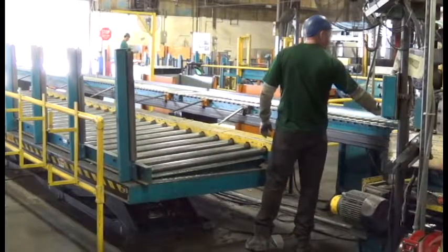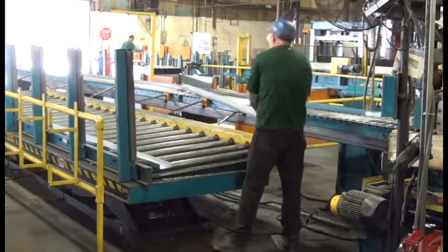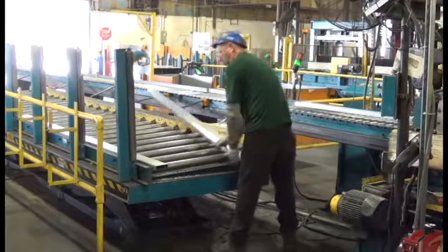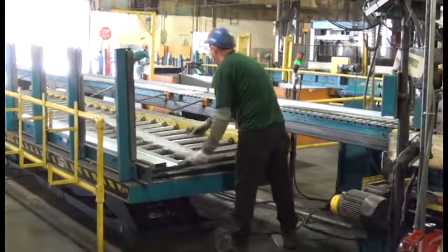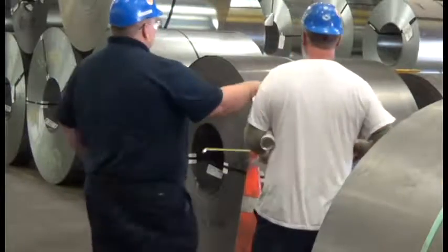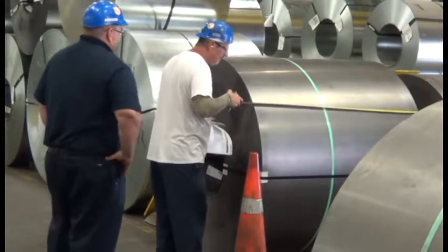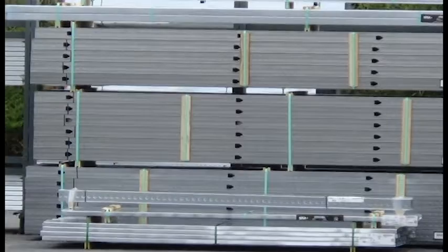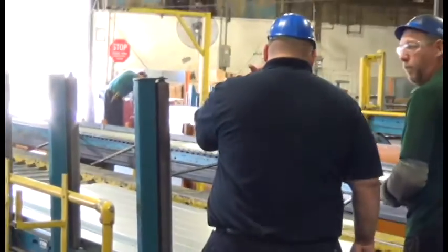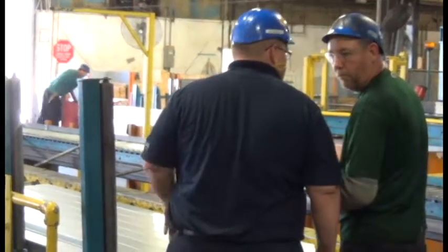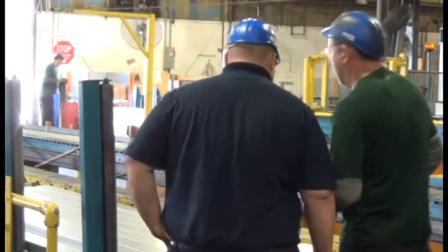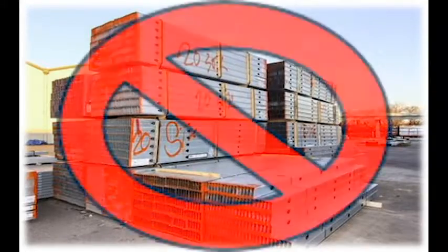A key benefit of traceability to the manufacturer is that if a stud or track fails a performance specification or does not meet minimum requirements, then it's possible to identify where the coil came from, possible reasons for the failure, and to identify any other products that may have been produced from that same coil. Appropriate steps can then be taken in order to minimize the chance of any reoccurrence. These additional steps may include marking and segregating the non-conforming material, adjusting your purchasing requirements or procedures, or having a discussion with your supplier.